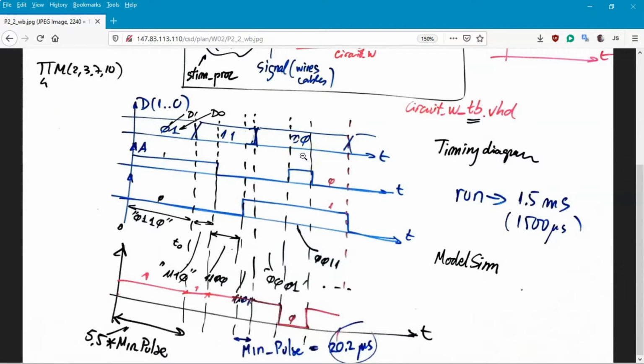And sometimes, for example, you are applying 0, 0, 1 and 1, and this is combination 3, and you know that for this combination 3, because it's a max term, you have to have a 0. So you know what is going to be the output of the circuit, and that is good. You are preparing this on paper, right? If not the final solution, because that is what the machine is going to give you, here you know even the final solution, because you know it from other methods. So that's all right, to have it all clear, if possible, on your paper.